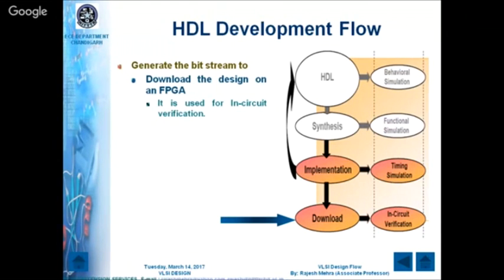Once this bit file is generated, it will set the different required bits. Let us say there are 500 programmable points in one PLD or FPGA, and each point is connected with 1 bit. So there are 500 bits, and when you design a particular system, let us say only 45 programmable points are required to be programmed. Those 45 programmable interconnects are associated with some bits in that long 500-bit file. Those 45 bits will become 1 and the rest will remain 0, and in this way your bit file will be generated.